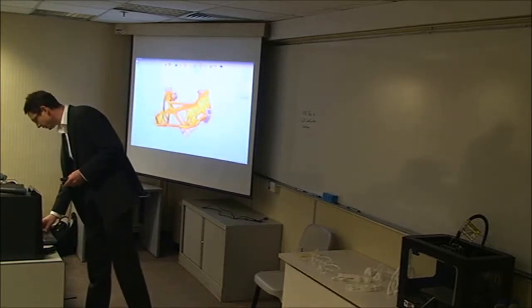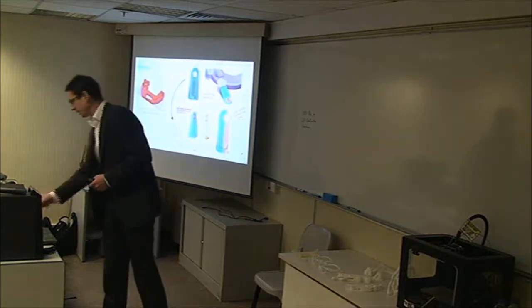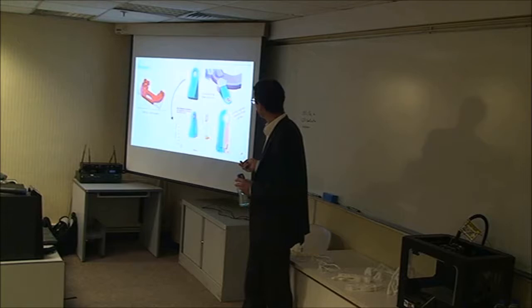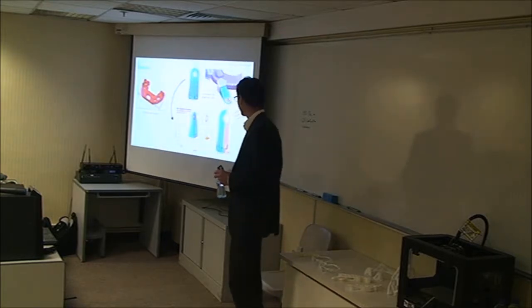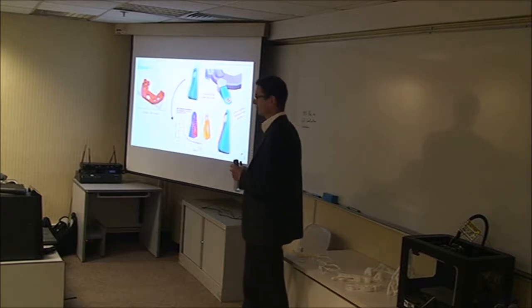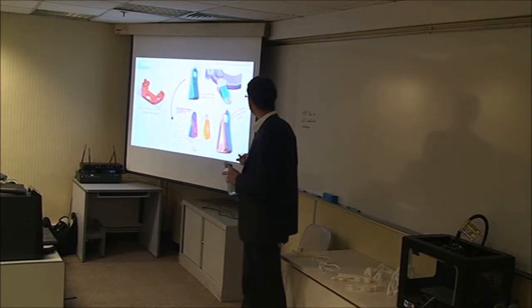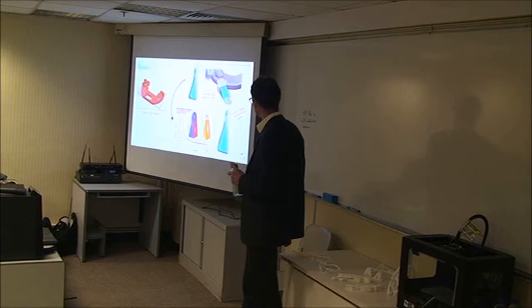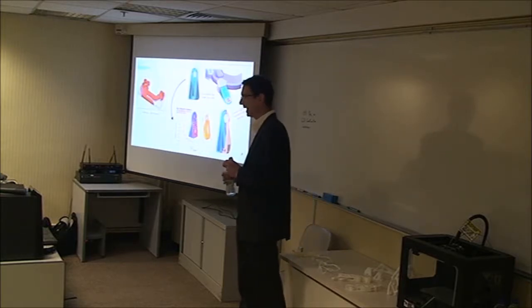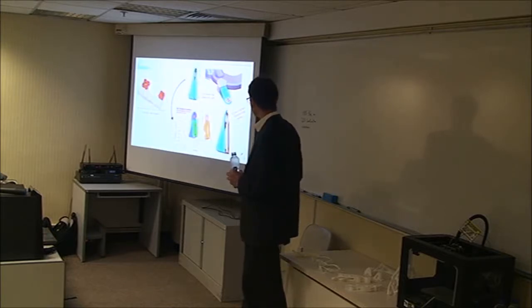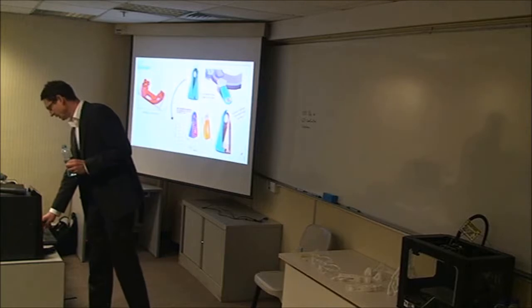Here is a practical example, or an illustration. You have a load on a part, you generate the shape, and later on you bring that into reality. That's an example for an automotive part. It was the end of the 90s when we simulated it. That part was a bracket that was not holding the loads. So we brought it into the simulation optimization method, and step by step the computer calculated where the material should be placed. And finally, the final design was lighter. You see a comparison between both, and it could hold the loads. So that is a very simple practical example of how that works.